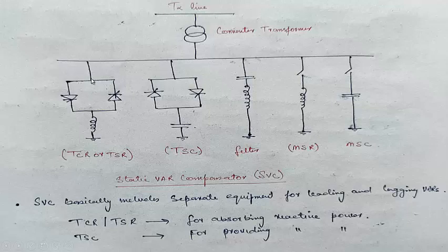It will be as if it is directly connected. There will be no control from 0 to 90 degrees. The control of current, inductive current in this case, that is for the inductor, will be from 90 to 180 degrees.